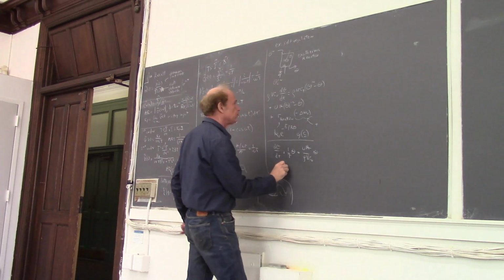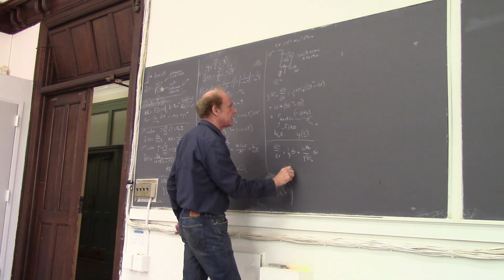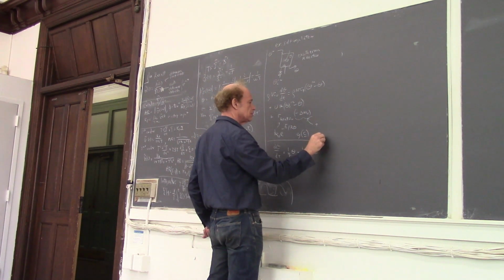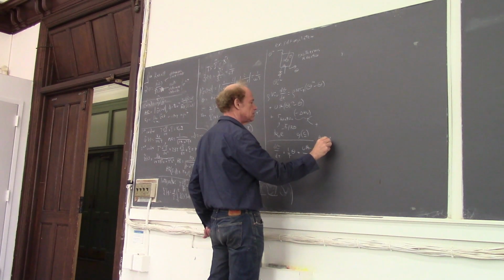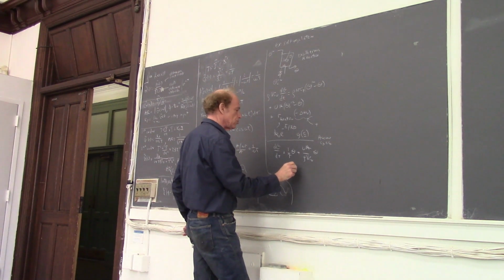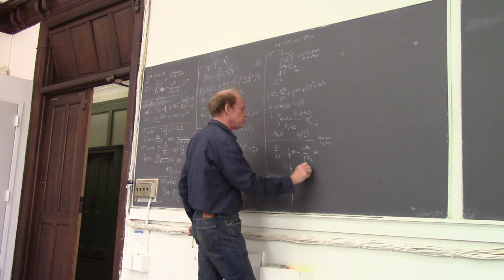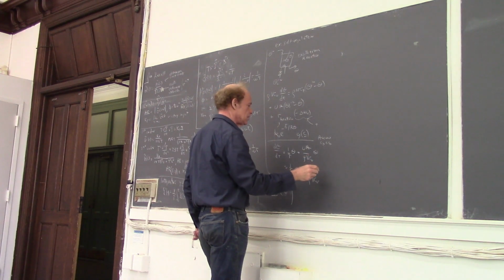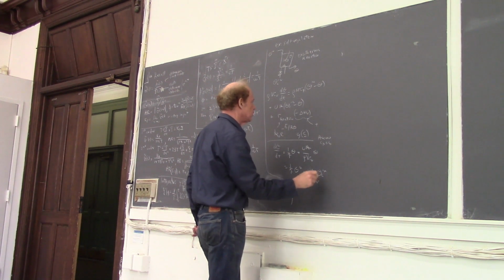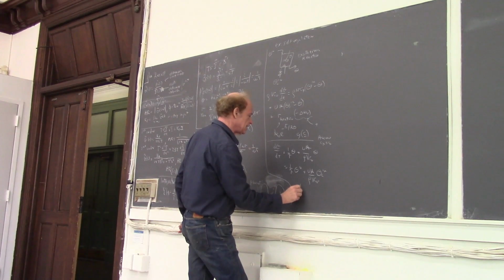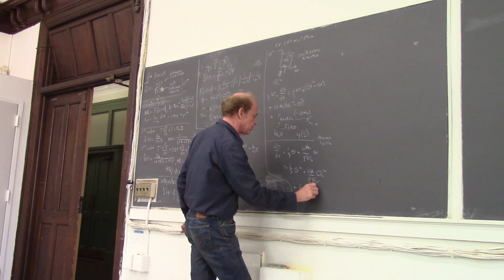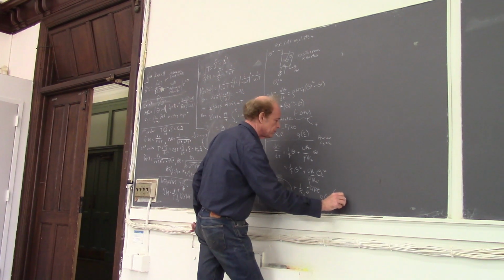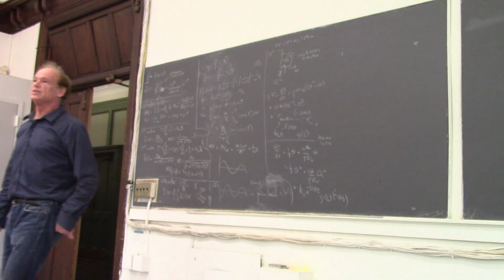And that's equal to what's left here, which is 1 over tau theta in plus UA over rho v CV times theta C in, where I'm assuming CV equals CP. And then I have plus k0 e to the minus E over R theta, some function of the concentrations, times minus delta HR.